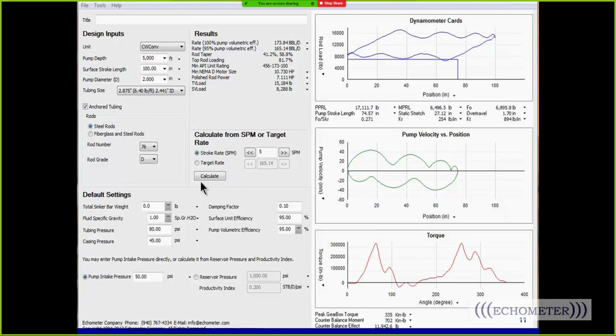Okay, one more question is from Tariq about the depth placement of a tubing anchor. Can you tell me what conditions determine the placement? I've been corresponding with him on the chat and talking about sand production and installation of the anchor above the perf, and when you have thin walls or are installing downhole gas separators, you don't want to install it below that arrangement because you may break the downhole assembly. But just go ahead and continue with that.